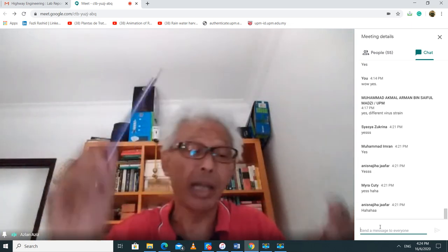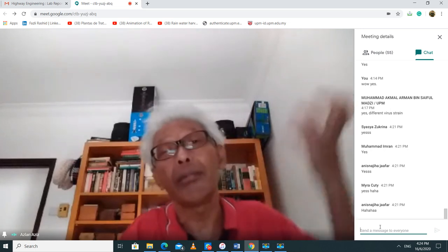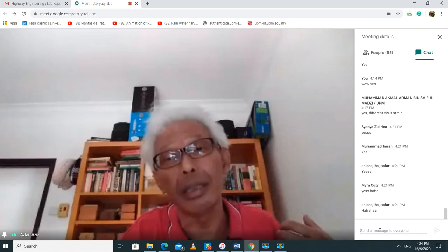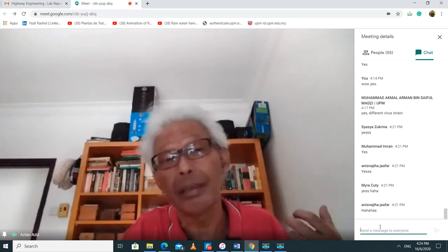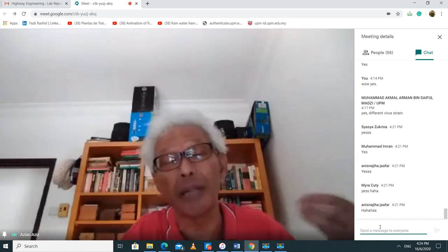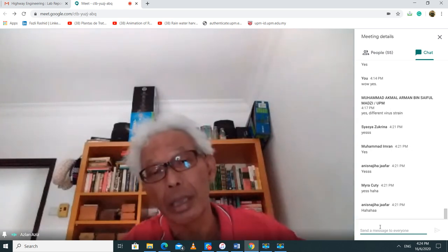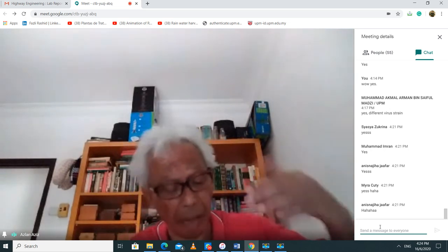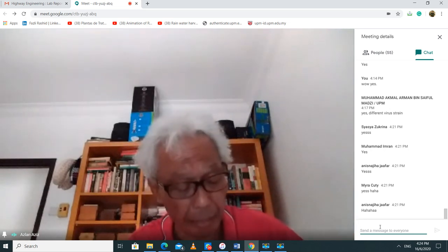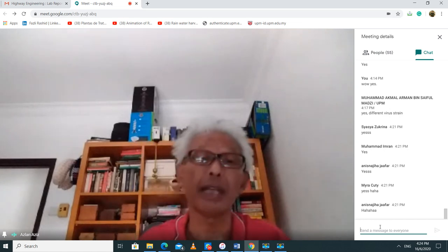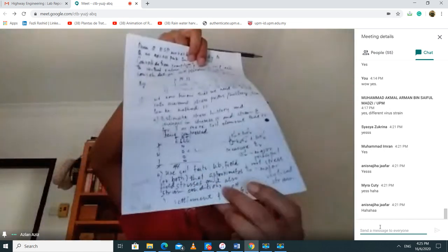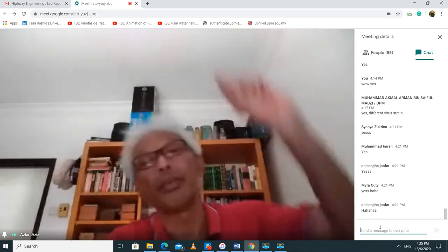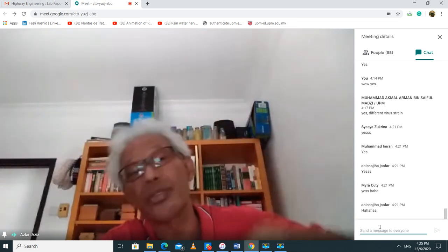Hopefully we can come up with a good decision. Well, in this one here, we take three or four samples, we do the test, and then we find the settlement from each of these elements, and those elements come from different layers of the clay stratum. Then we just add them up in terms of the settlement, and that's what it is at the bottom here. If you get one settlement from one element, then we just do the integration.